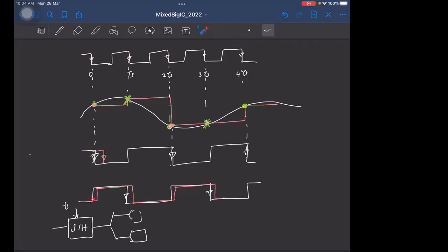Similarly, the same holds good for this also. Even if there is a delay in this clock, you will be sampling at, say, one of these time points, right? But the signal value at this time, or during this entire period, is equal to the signal you had sampled at this TS. So as long as this clock has well-defined sampling instances, which of course you wanted, because even if you want to have a full rate ADC, you want a good clock to sample the signal, right? So let's say this is a given. As long as these sampling edges are defined properly, there will be no offset issue. That is, no issues due to this timing skew.